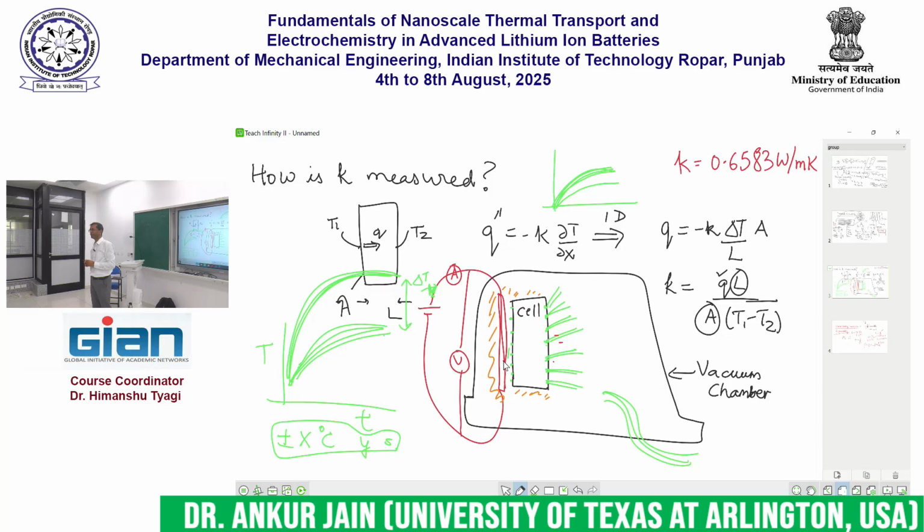You don't want to do this repeatability measurement on one cell that I purchased today and another cell that was lying in the lab for 1 year, was probably leaking a little bit, right? That's not what you want to do. 5 identical samples should give you relatively similar thermal conductivities. Does that make sense? Any questions?